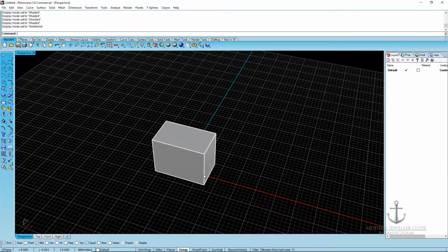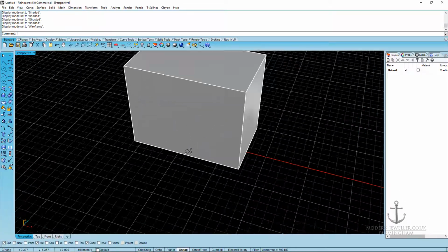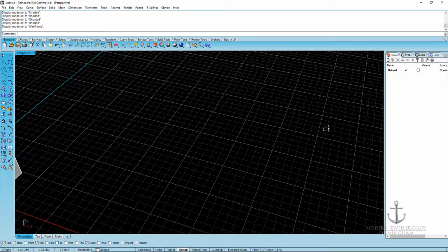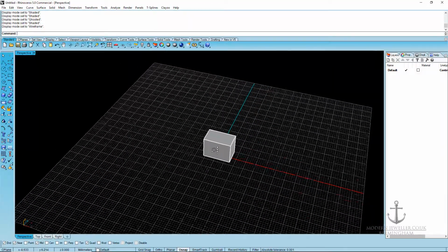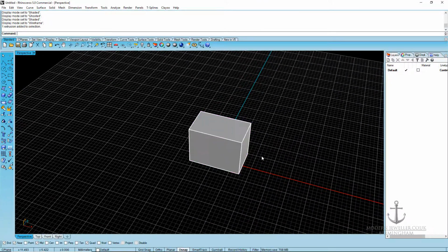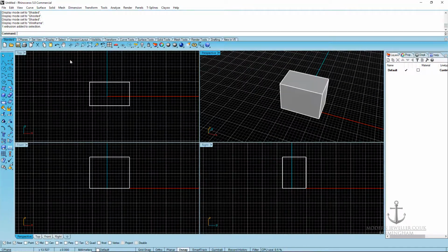If you hold the Control key on the keyboard and the right-click button, by moving your mouse up and down, the zoom command will be active. Also, you can do it by scrolling the middle mouse button. I minimize the perspective viewport by double-clicking on the title. In the rest of the viewports, you can make the pan command active by just using the right mouse button and dragging inside the scene.